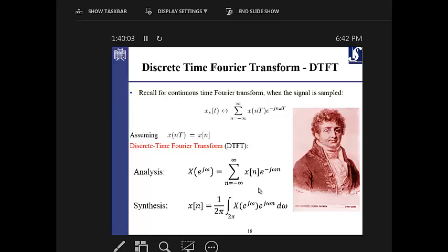So that's the meaning of the Fourier analysis, which completely goes to the frequency components and takes out the frequency values of the signal, how much from every frequency it contains. We know that the frequency in the discrete domain changes from 0 to 2 pi, or from minus pi to pi. So the entire period is nothing but 2 pi.